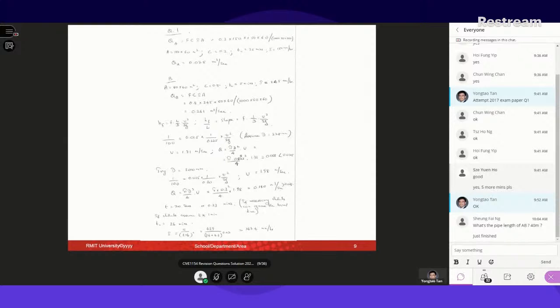So firstly, to get the intensity, from the table or use the equation. Now for the parkland, the time of concentration is 25 minutes. So from the table, you can find the ARI, 20 years. So you can find the intensity, 150.